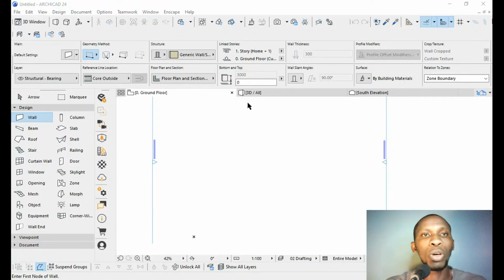So let's use symbolic cuts here, and for these particular lines, remember we set our pen widths. On these cut surfaces, we can see different line types. You can make use of any type of line here, but I usually make use of straight lines for block walls. For solid cut lines, you're making use of straight lines. Then for cut line pen, we have 0.35 millimeter here.